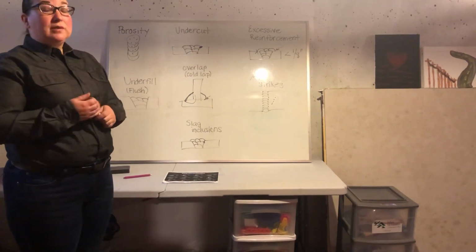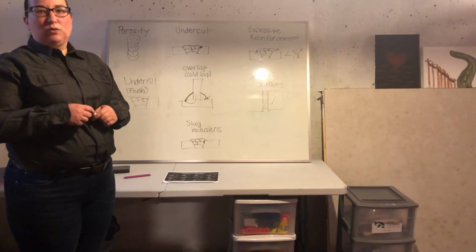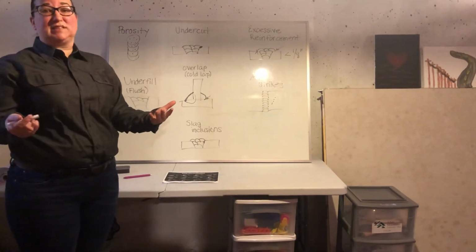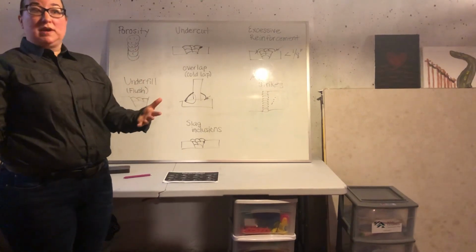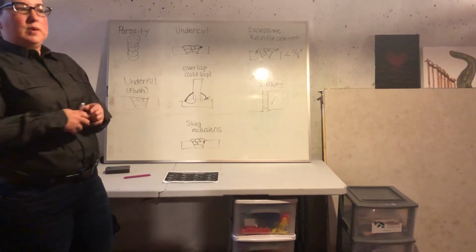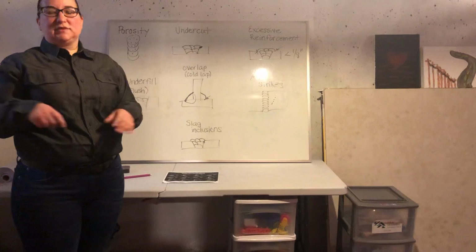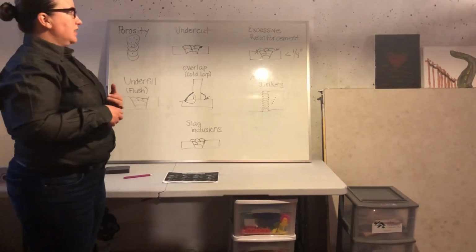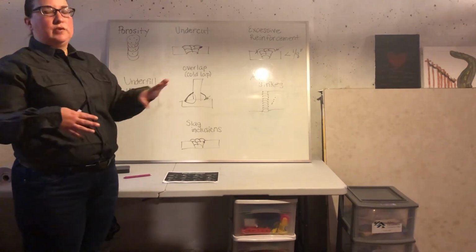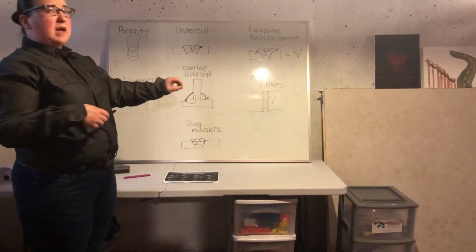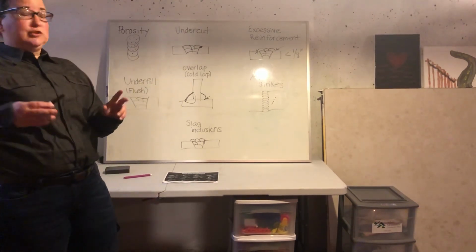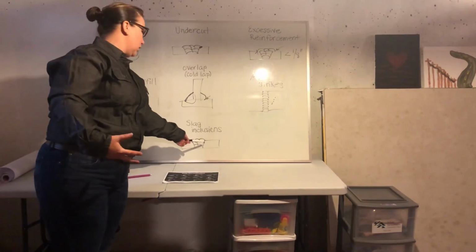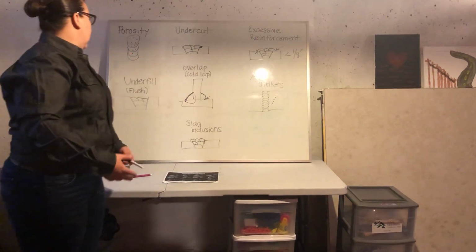This is really, really important to nice sound welds, and also really important to passing visual tests. As we become welders for a career, we may have to take several tests, whether it's for a company or for the American Welding Society. These weld tests are going to look for these discontinuities. Some of them may not be apparent from a visual test. So like a slag inclusion in here, we're not going to see that with a visual test.